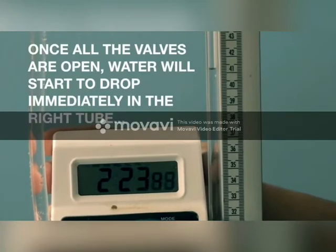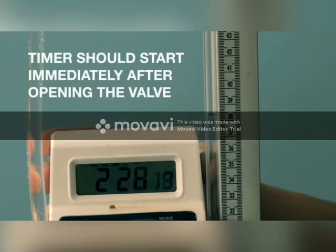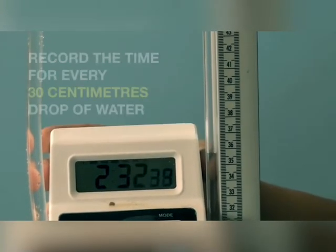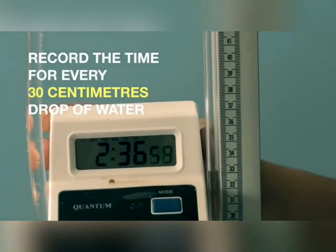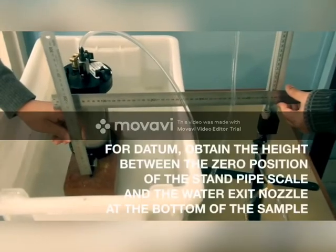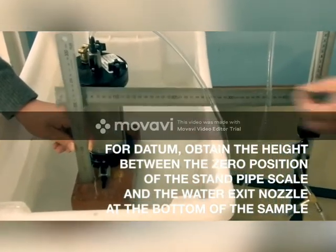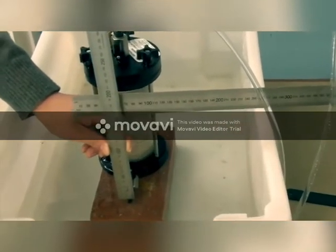Once all the valves are open, water will start to drop immediately in the right tube. The timer should start immediately after opening the valve. Record the time for every 30 centimeters drop of water. Then, for datum, obtain the height between the zero position of the standpipe scale and the water exit nozzle at the bottom of the sample.